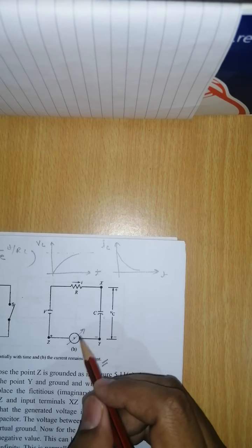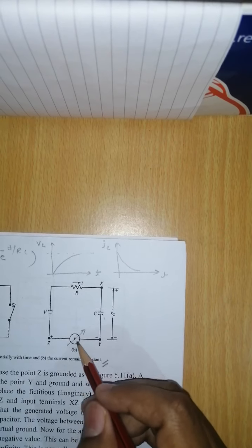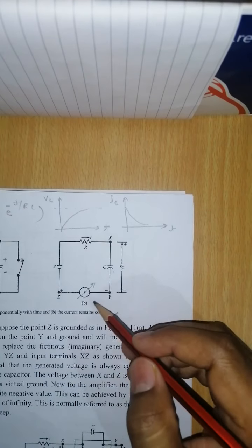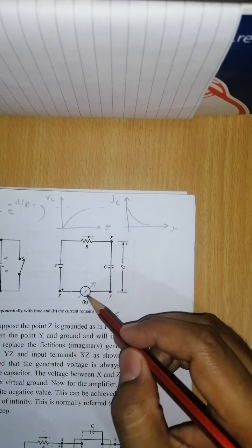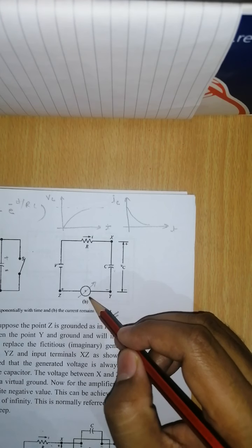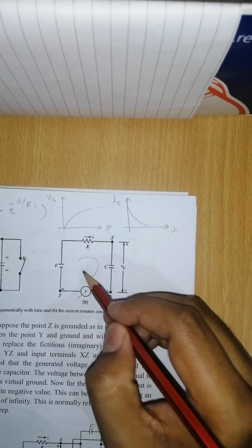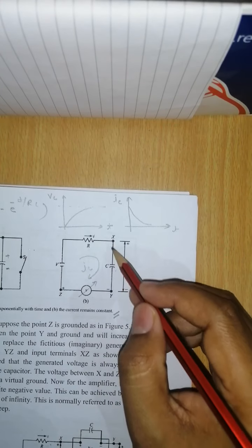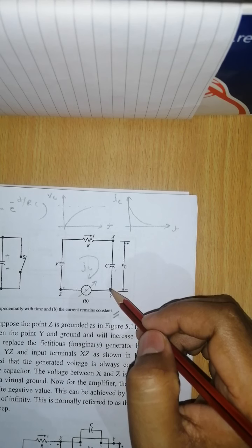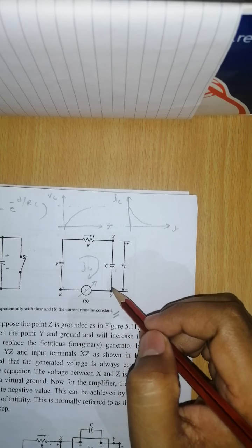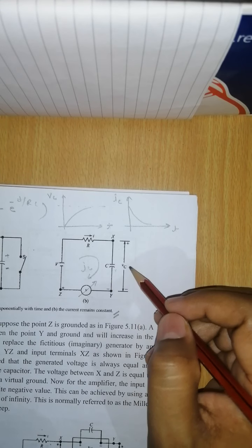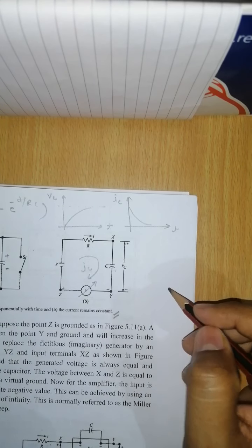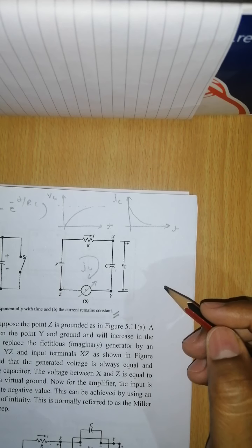So this is a fictitious voltage we are connecting in this. By connecting this voltage, what advantage are you going to get? The advantage is simple. Whatever voltage is coming across this capacitor will get nullified by this fictitious voltage. So what happened? The current through this capacitor is not going to decrease, and it will charge in a linear manner. That is actually the basic requirement of generating linear waveforms. So that is the basic phenomenon of the Miller principle.